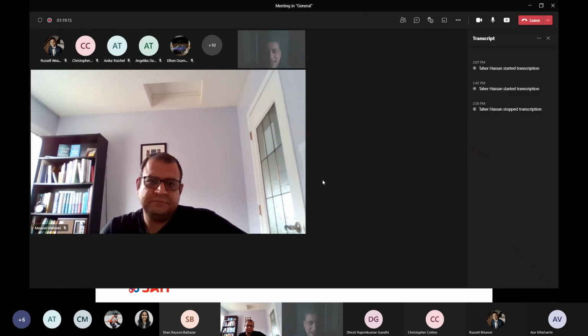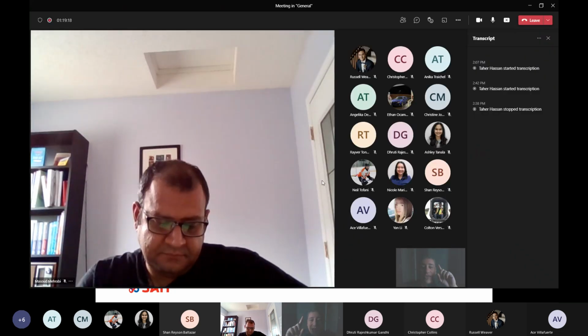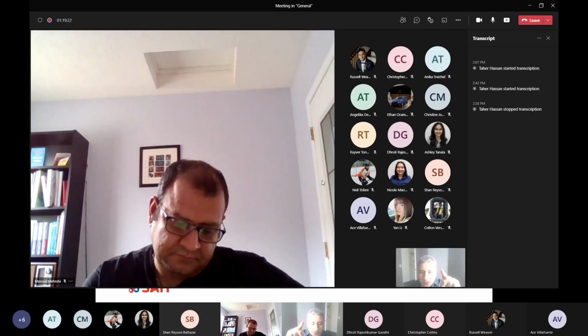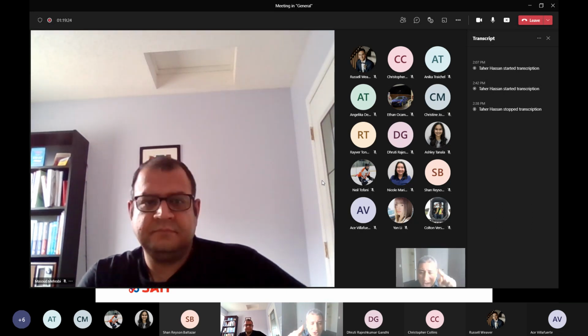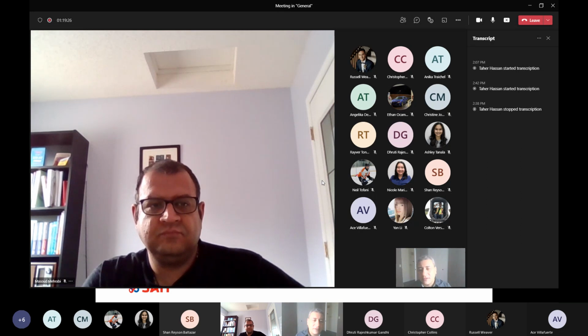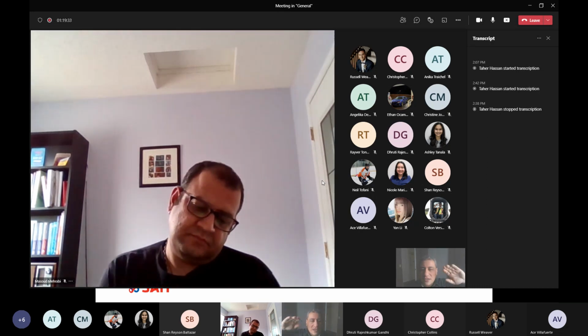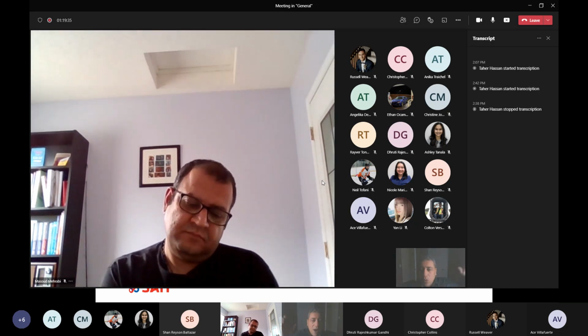What does horizontal mean? Mathematically, it means without adding extra stress, we get more strain. Do you get that? Look, when the line is horizontal, it means the stress is constant while the strain increases. If you agree, give me thumbs up. I'll show you the curve.